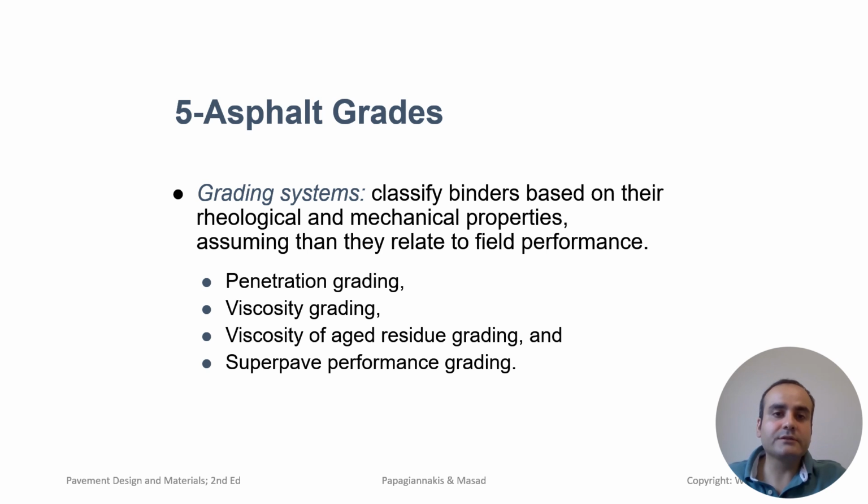There are also some other advanced techniques, which are the common techniques used these days, such as the performance grading technique (PG system), which is a newer, more comprehensive system that evaluates the asphalt binder's performance across a range of temperatures and under varying loads.